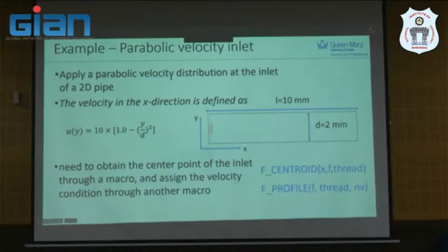And we will use this macro and this macro. This one is used to obtain the center point of the inlet. And this one is after we calculate the value, and we will return the value to this macro. And this macro will set the value to the boundary of this simulation domain.